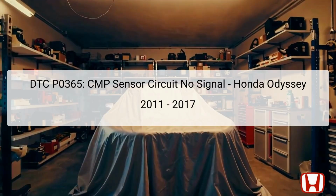DTC P0365 refers to a diagnostic trouble code that indicates a problem with the Camshaft Position CMP sensor circuit, specifically a no-signal condition. This code suggests that the sensor is unable to communicate its data effectively, which can lead to various engine performance issues. The CMP sensor is critical for the engine control module, ECM, to accurately determine the position of the camshaft, which in turn influences the timing of fuel injection and ignition.